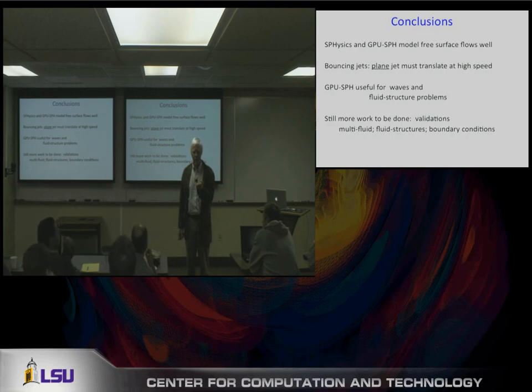But the problem is, I've got these big blobs of fluid, right? And so if I just care about the boundary layer, then I can do it, because I'll just make my particles really tiny and get a whole bunch of them inside the boundary layer, and then I'm done. But if I'm doing a problem like that ball floating in the wave, and I really cared about the boundary layers, then I have this problem, because my particles are big and my boundary layers are small. And so if I do nice angular objects, where the flow separation is pretty obvious, I think things are pretty good.